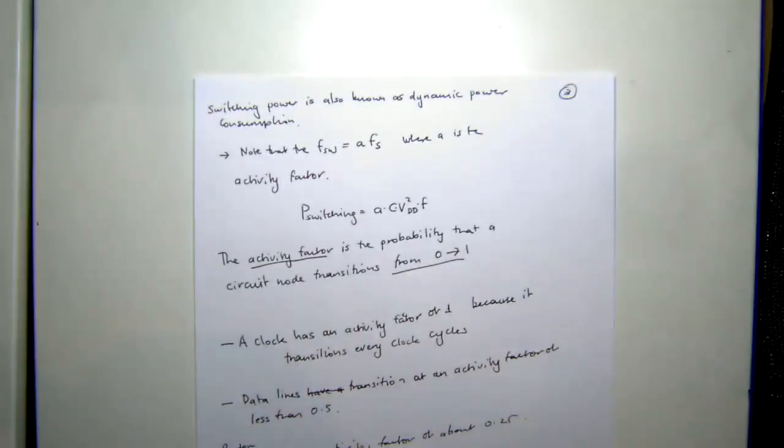So in a synchronous device, what's the element that's always switching, changing? The clock, right? So that has an activity factor of 1.